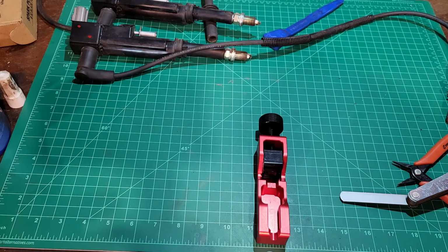There's a few things. It doesn't have a mass airflow sensor. There's a few things like the fuel pressure regulator. Unfortunately, it's part of the fuel pump in the tank. Could be giving it more fuel, could have an injector stuck open or staying open too long. Anything like that, but we need some kind of baseline.